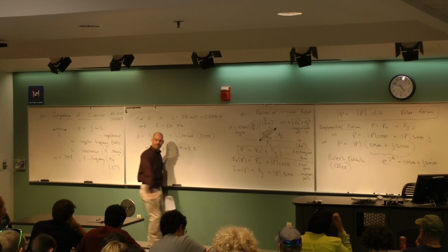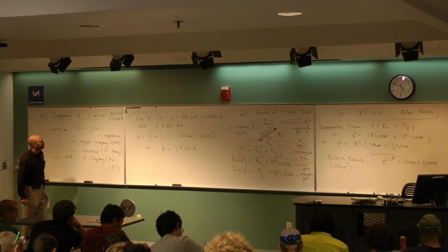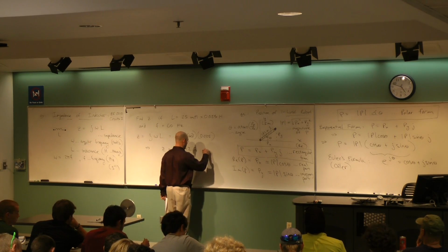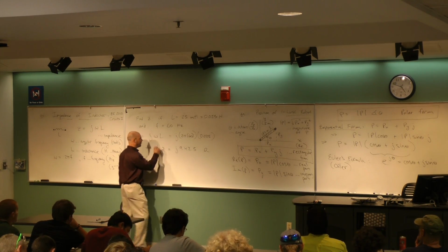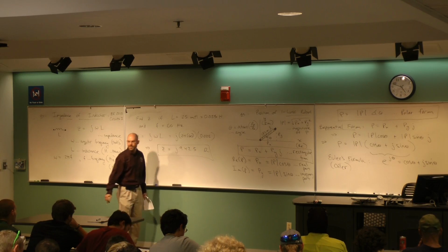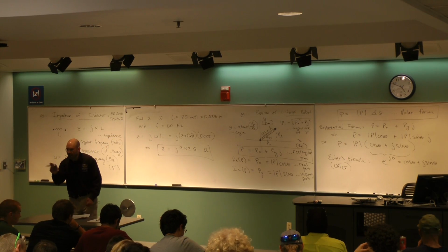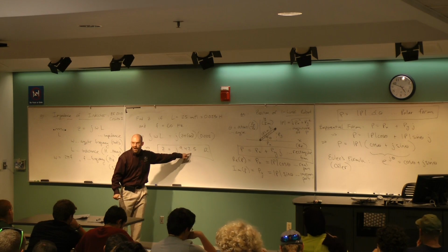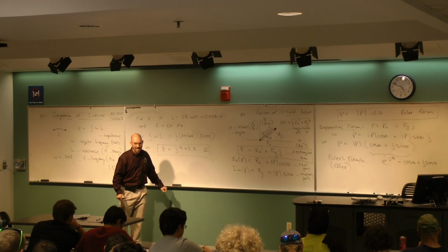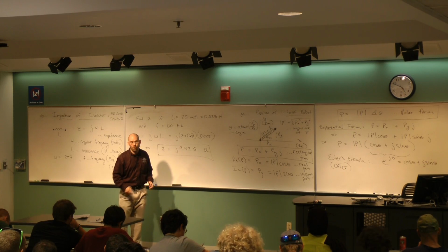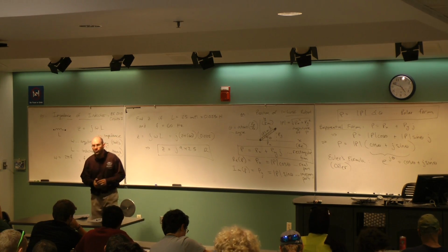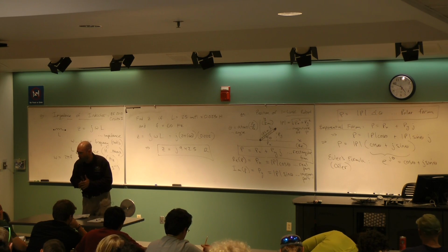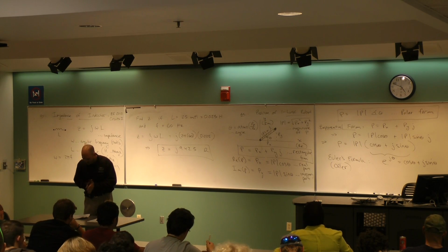Units on this. Impedance. Generalized resistance, right? Resistance is in ohms. So this is the way you would actually write down the impedance of an inductor circuit element. It's an imaginary number. 9.425 isn't an imaginary quantity. You could measure it. It's in ohms. So the point is we use the J for this circuit element. Other circuit elements have other definitions. We will work on those next time, and then we'll start solving some good problems.